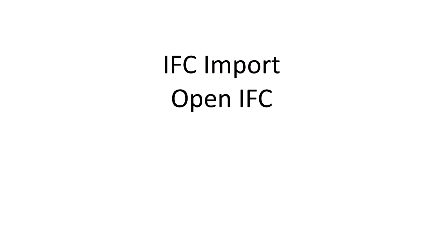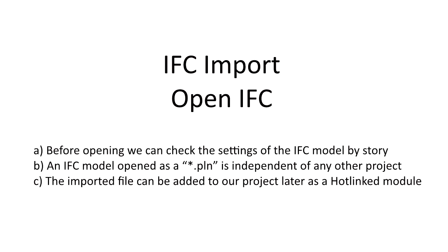Advantages of Open IFC are: A. Before opening, we can check the settings of the IFC model by story. B. An IFC model opened as a .pln is independent of any other project. Or C. The imported file can be added to our project later as a hot-linked module.